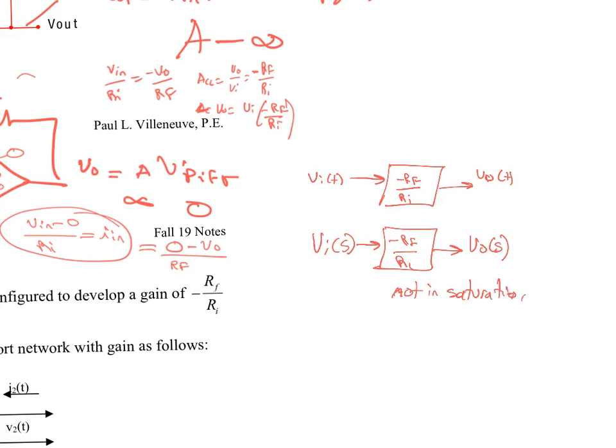By the way, how can you tell if an op amp is saturated? You have to look at the rail voltages, right? So if the rail voltages are plus 15 to 0, if you're pushing 13, 14 volts on your output, you're getting close to saturation, okay? So in the real world, we can't say, oh yeah, I'm going to take a 5 volt input and get a 500 volt output, because that probably ain't going to work too well. You can do some of that with power electronics. That's completely different, but your rail voltages had better be 550, 600 volts, right? You would need pretty high voltages.